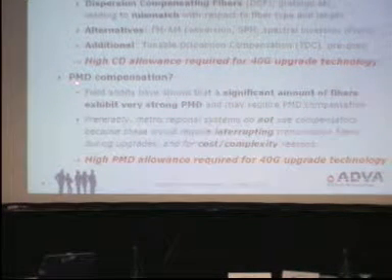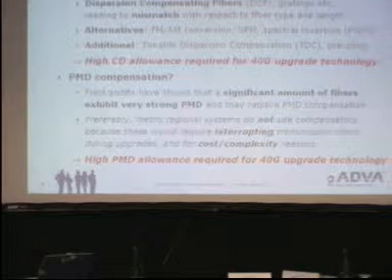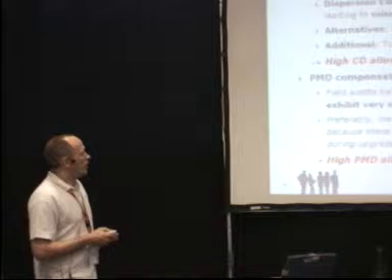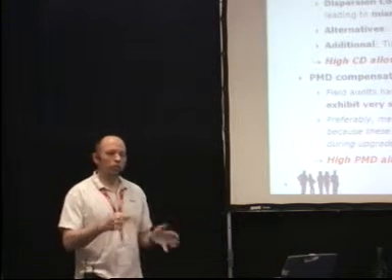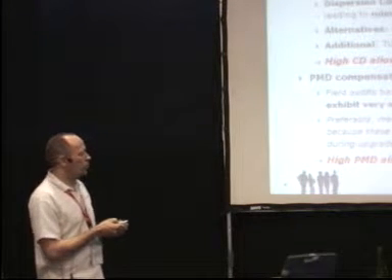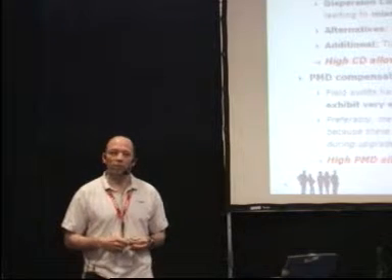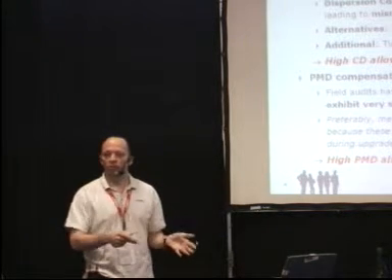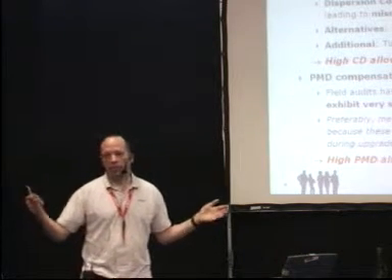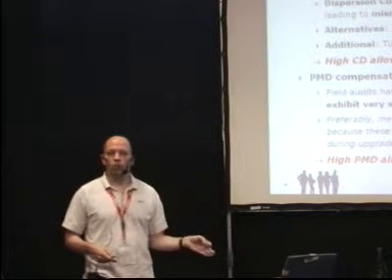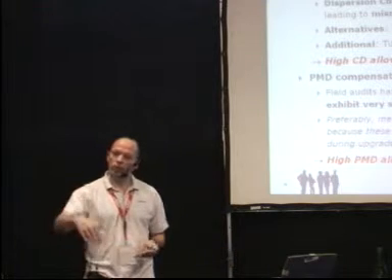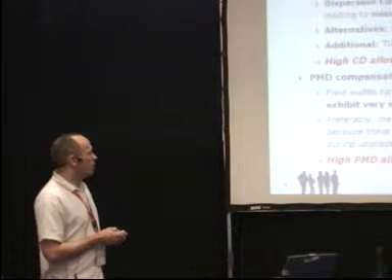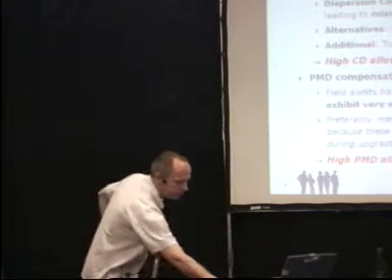But it's getting even worse because polarization mode dispersion may now become the most serious effect. I will come to the field audits on fibers. Next slide. We have an additional requirement with the simple low-cost Metro WDM systems, which is, if possible, do not require PMD compensators. For example, because PMD compensators today are not off-the-shelf components. They only exist in the laboratories. Plus, if it's an existing link which shall be upgraded, placing a PMD compensator would mean opening the fiber, shutting down the link. Not a nice thing for existing installations. So the next requirement will be highest possible PMD allowance for the 40 gig technology.